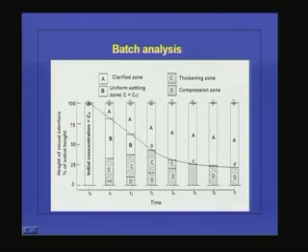Then at t2 again we take the height of the clarified zone, and like that we go on, and after some time we can see that this depth is not increasing considerably, or the curve is becoming almost flat. So, this information we can use for the design of the clariflocculator.